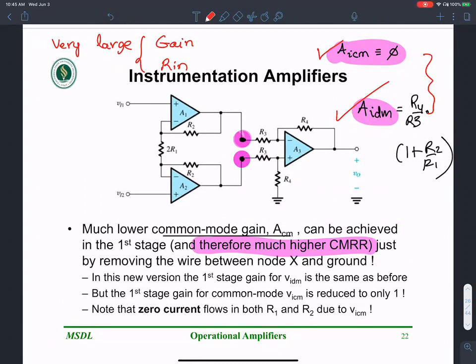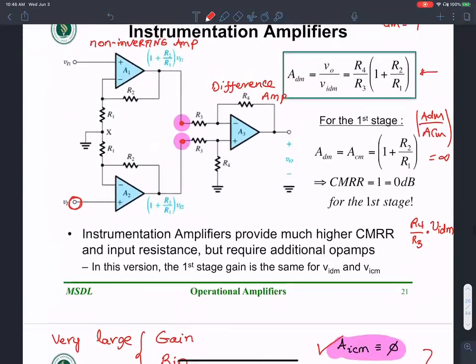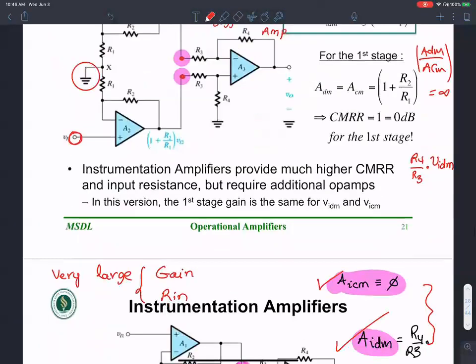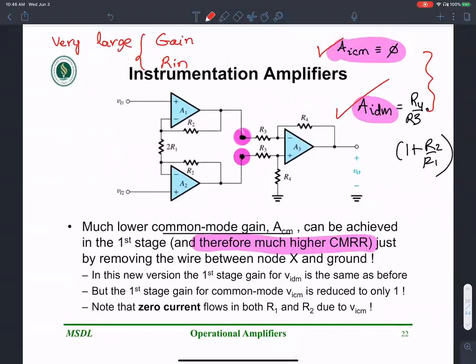I have a question. Professor, yes. I was trying some of the problems, like the exercise for meter 1, and it turned out the common mode gain for this circuit to be 1. For the above circuit, it is 1. Yes. Okay, for the one that you have in the following, without the ground? Without the ground, that's going to be 0. The common mode gain will be 0. Okay. Other question, please.